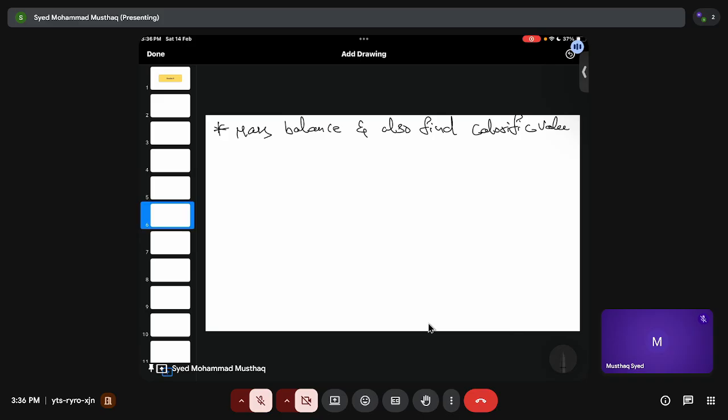Whenever you burn it, there is also this water. Water vapor will take energy and become superheated steam. So again, some amount of energy is lost there because steam takes energy, right? So in net calorific value, we avoid that part. Okay.